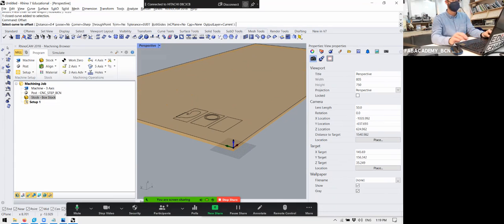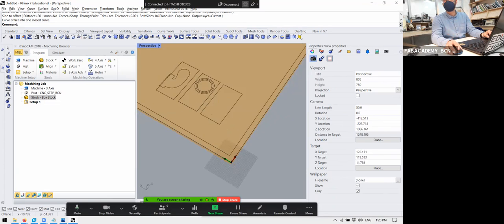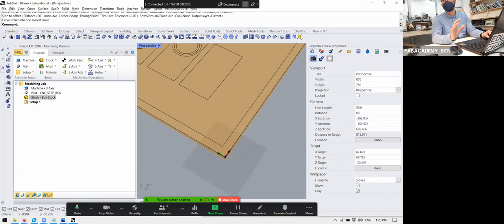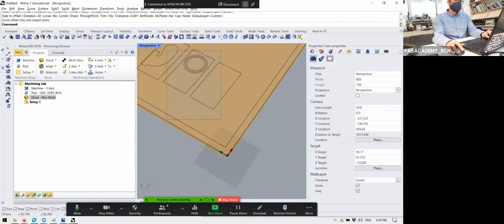So I make an offset of 20 millimeters. In that area, I cannot place any object. Usually, I even leave a little bit more, 30 millimeters, because I know that I can easily put all the screws I want next to the corner. I will never have anything there. It's the safest hold down practice I can use. So we have this design.